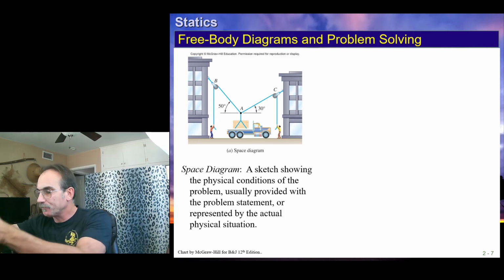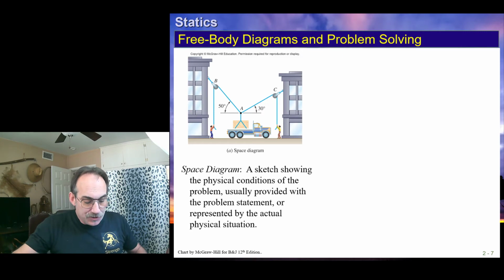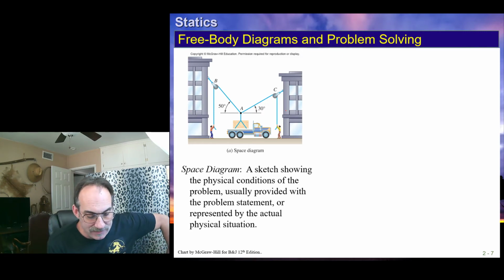For example, if we were to cut this, and we call the tension in this cable T1, if we cut the cable here, we can see that that cable is going to have a tension of T1 on both sides. We've got the part down here in the little man's hand, and the part up there, and looking at this part of the cable, we could see that's in tension T1, and looking at this part of the cable, that's in tension T1.